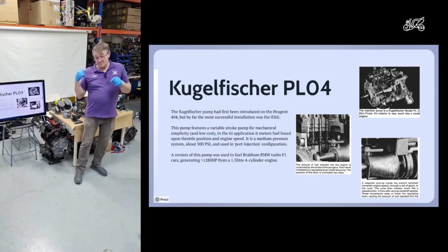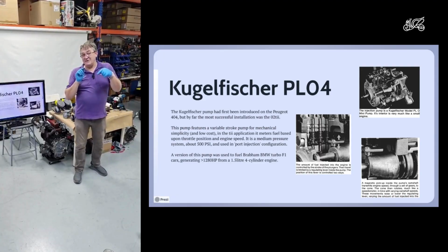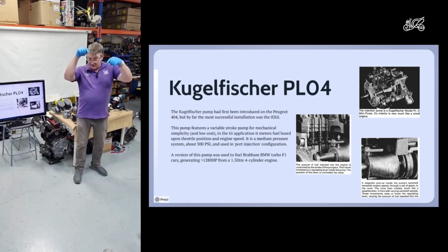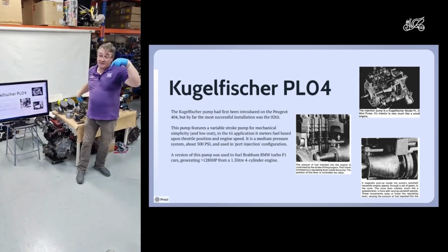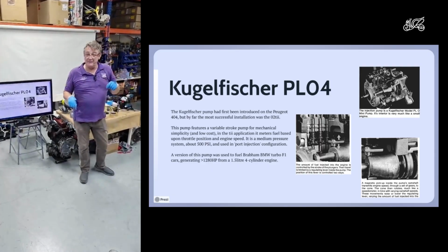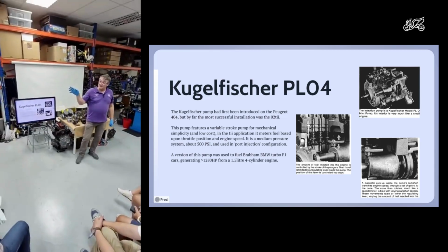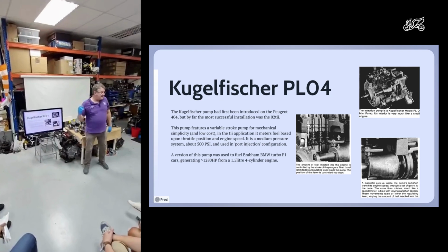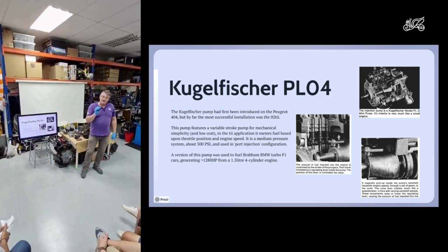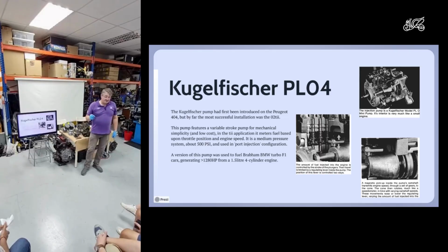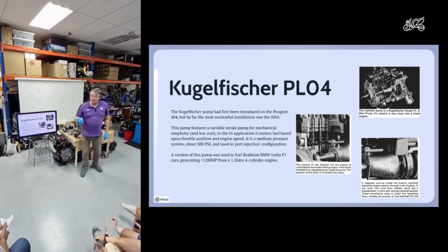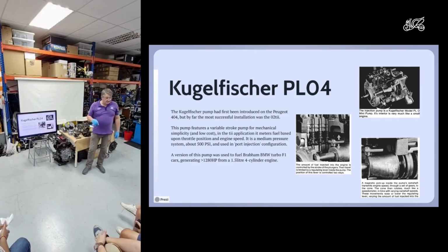You can't do that. But with this pump, I can time the injection. So the exhaust valve is still open, and at that point, I'm just blowing in air. And then as the exhaust valve closes, with the cam shape, I can start to inject the fuel, and that way I can ensure that no fuel goes out the exhaust. So with the mechanical system, I can time the injection with the valves of the engine in such a way that I can efficiently and without any side effects get the fuel into a turbo.